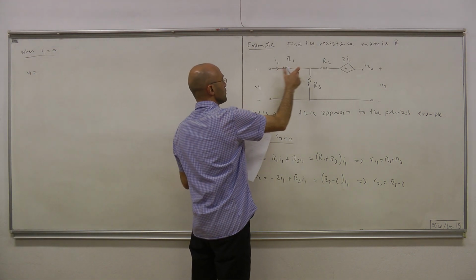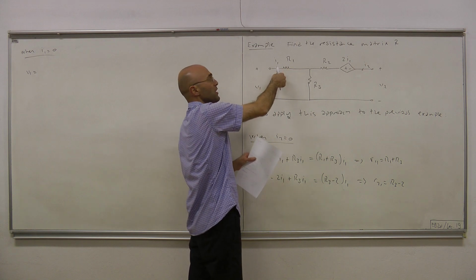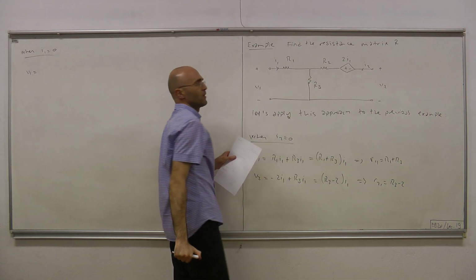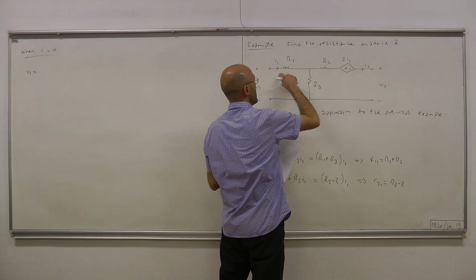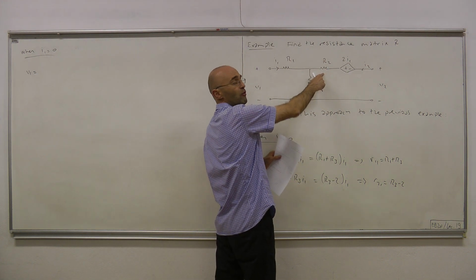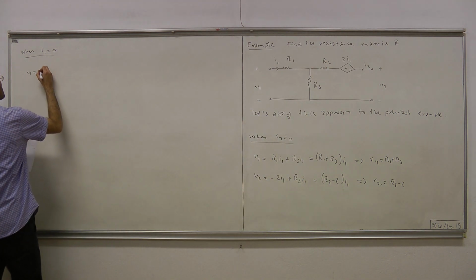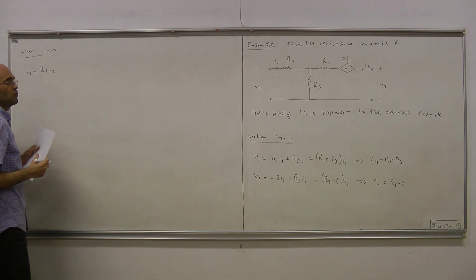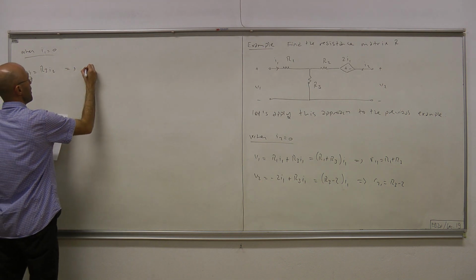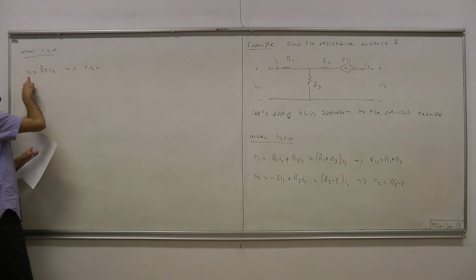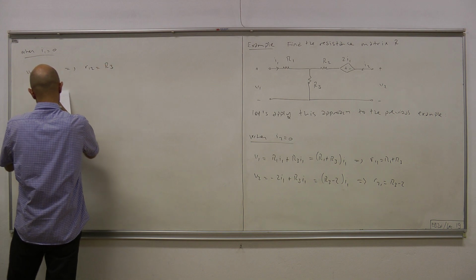V1 equals this voltage plus that voltage, but now this voltage equals 0 because I1 equals 0. Okay, there is no voltage drop across R1 in this case. And what's this current? We have 0 current coming from here, I2 is coming from here, therefore it's automatically I2. Hence V1 equals R3 times I2. Okay, and that means R12 equals the ratio V1 over I2, which is R3.